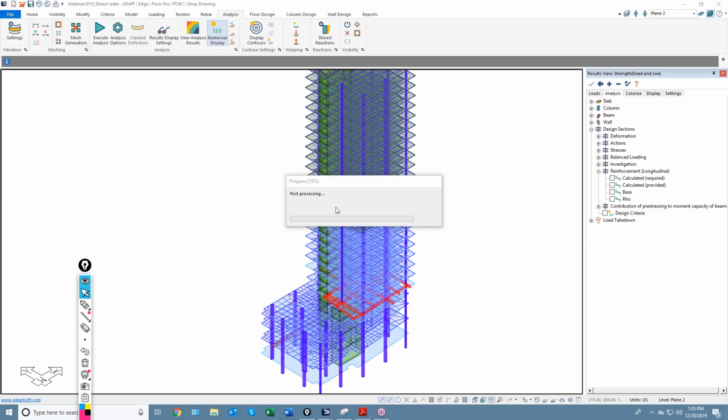This mesh, I meshed this model at 7 feet, so that's a pretty coarse mesh, but the model runs fine. It's stable and no issues there. But if I was actually doing this for design, I'd probably back that down to 4 or 5 feet for the mesh, or even less.